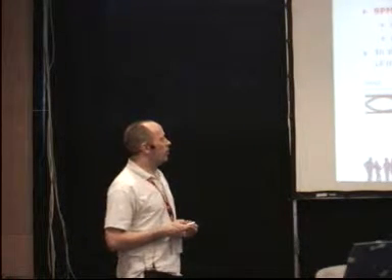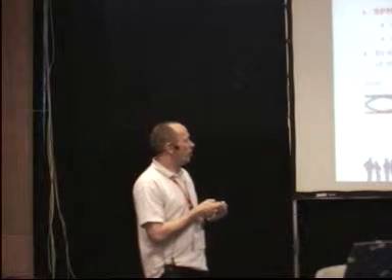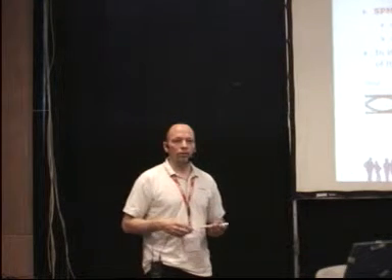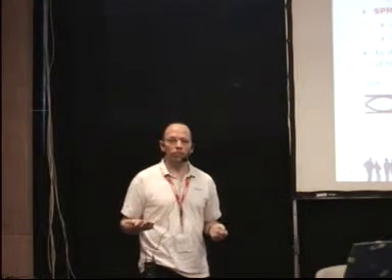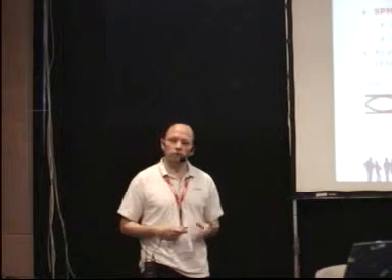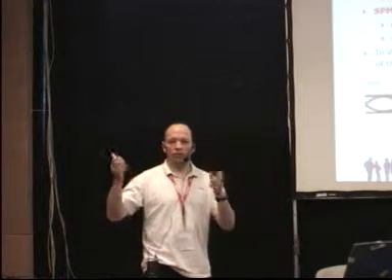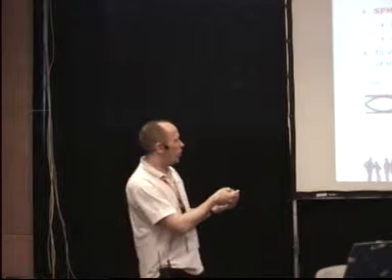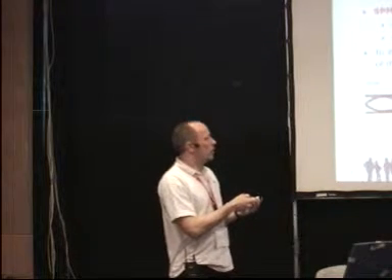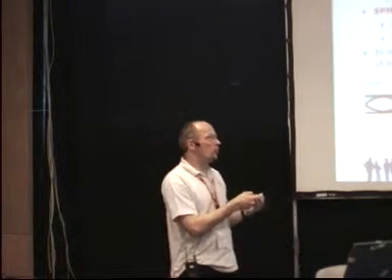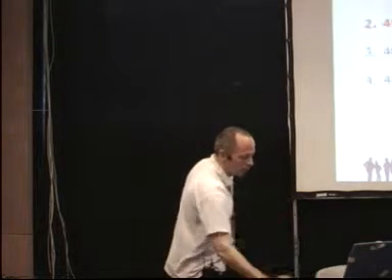And the good news is the plus sign is easy to achieve. Use standard G.652 single mode fiber and use standard DWDM wavelength, then you are here. But still the effect depends on modulation. So if possible, we want to use this effect by proper intelligent modulation.